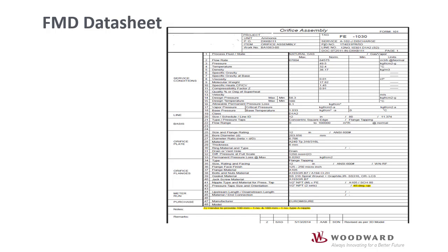The next important document is flow device calibration. Essentially, we need this document to define the relation between the differential pressure generated by the installed flow measuring device, such as orifice, venturi, pitot tube, and so on, and the corresponding flow which is used for compressor control. The flow Q is equal to differential pressure multiplied by a constant. This constant factor, which is also known as the C term, is determined by this datasheet.